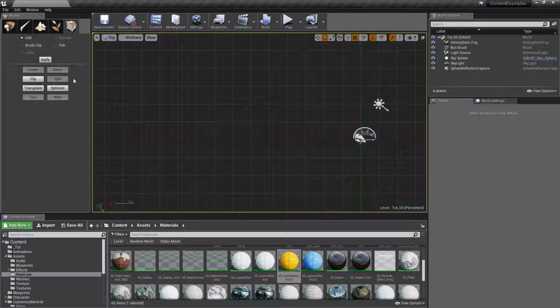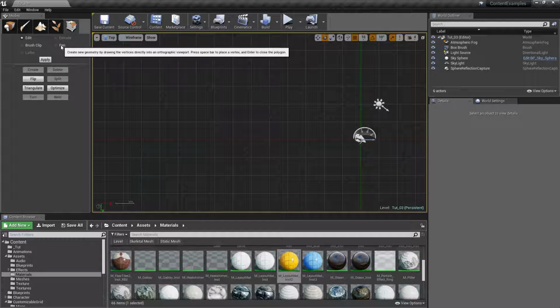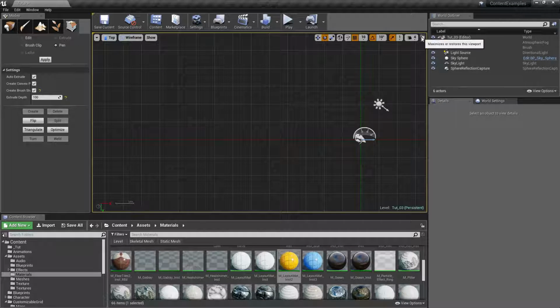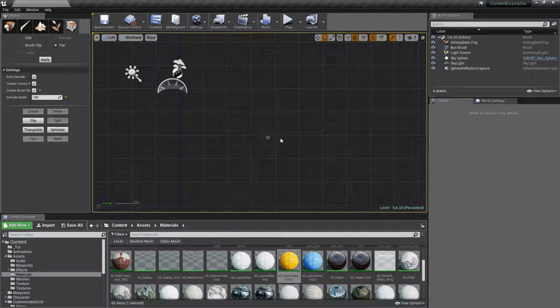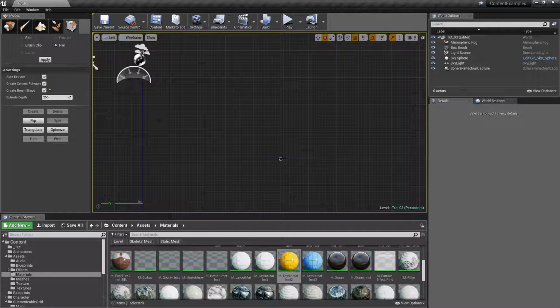And we need that pivot point because this thing says create a geometry by rotating the selected brush shape about the current pivot point. So we need a pivot point, but before that we need a brush shape, a custom one. And to do that we need a pen tool. And I'm going to go into a left view, so I can draw a profile of a pillar. I'm going to make a pillar. And you have to select this create brush, and this doesn't really matter when you're doing this. Create brush shape, and you start drawing, and you should make something.